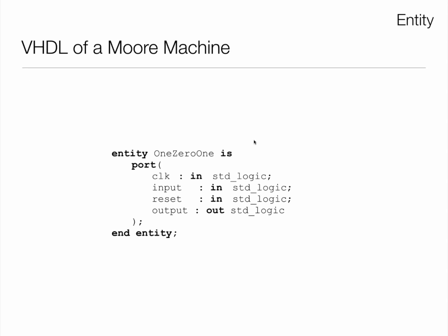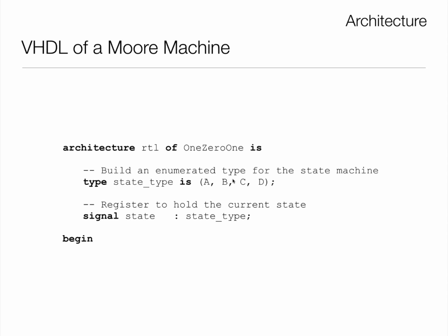It's just as easy to do it with a shift register and a few gates, actually, but it's an example we can work with. So we have the entity for a device for detecting this. I've called it a 101. It's got a clock input, an asynchronous reset, and an output. Okay, the architecture, we'll look at a bit of it now.